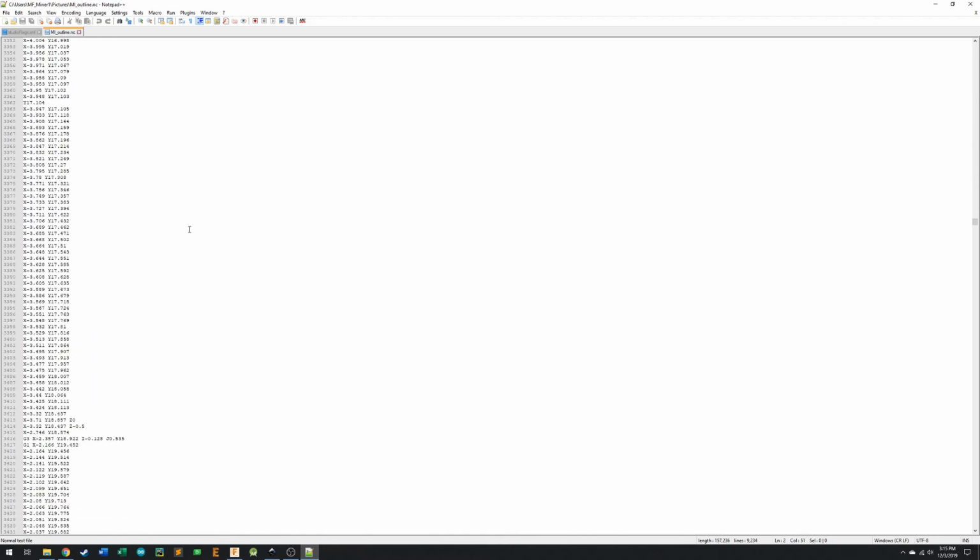And then at the very end, I mean, we're already at line 3000. I've been scrolling for forever and a half. Once we scroll all the way down, we've got just over 9,000 lines of G code here, which is pretty cool. We've got our M commands and our G90, which is return home and set your X and your Z to 0 and everything like that. And that's all we need to get our G code.